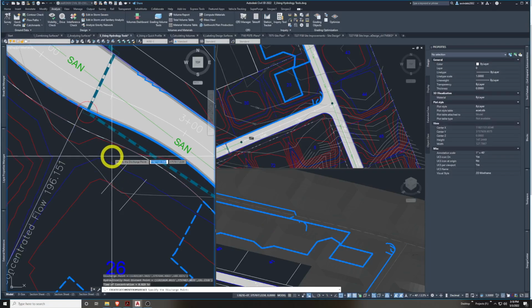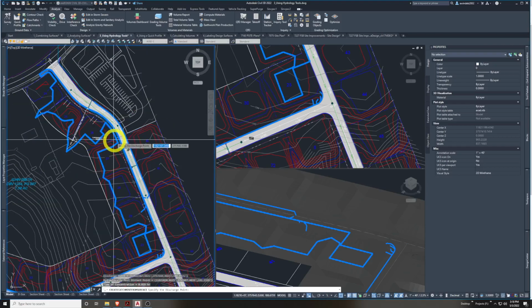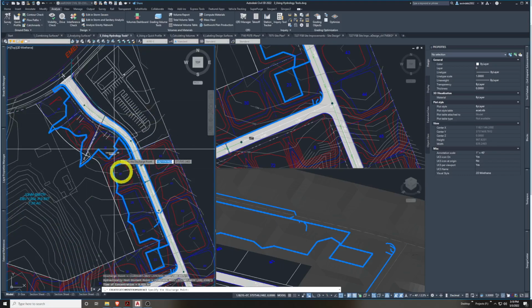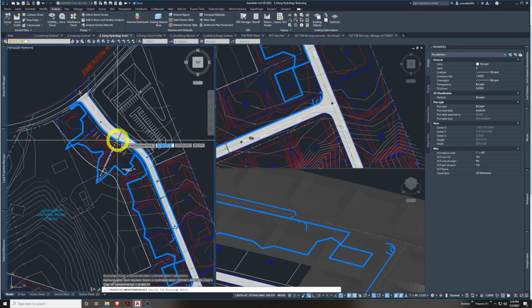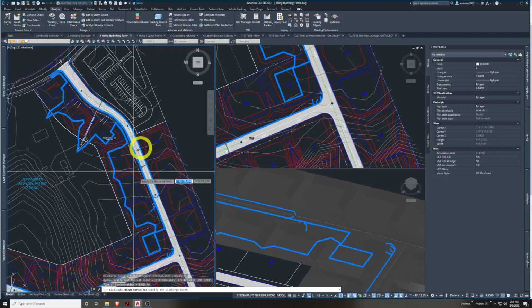So now the blue outline indicates the shape of the catchment area that drains into this inlet location that we selected. So we knew this is kind of a low point. We're getting this big theoretical blue blob here. This is the whole theoretical area that would go, based on our design surface we've made, into this catchment area. So it's saying, hey, this is the area you were picking of your design. This is theoretically how much 2D area will drain into it in this new post-development area. It's very helpful.